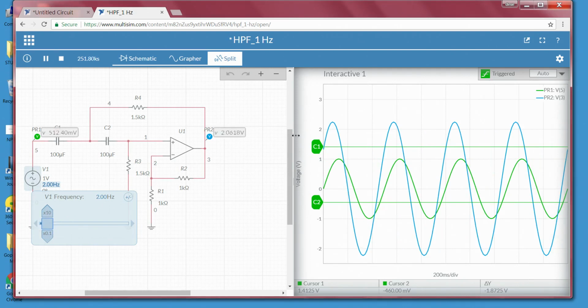Now, if we carefully observe our characteristics, whenever it comes close to the cutoff frequency, the amplitude is a little higher, even here we can observe at this point. The gain should be 2, but there is a slightly higher gain at frequencies close to the cutoff frequency, as we have seen. This is because of our Butterworth filter, it is a second order high pass Butterworth filter. When we recall our Butterworth filter characteristics, the gain will be slightly increased near the cutoff frequency.